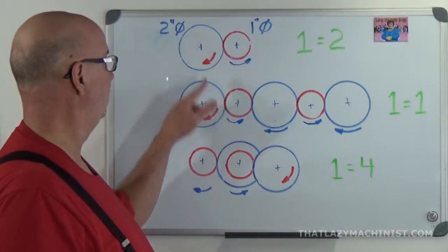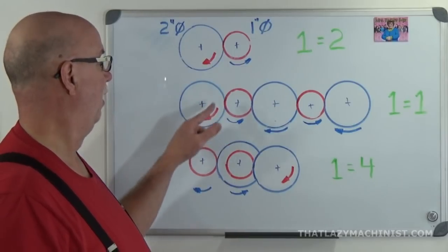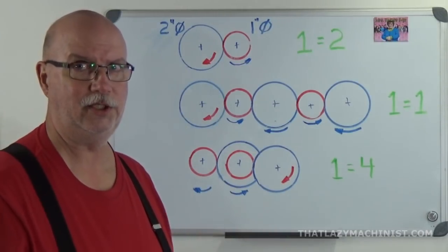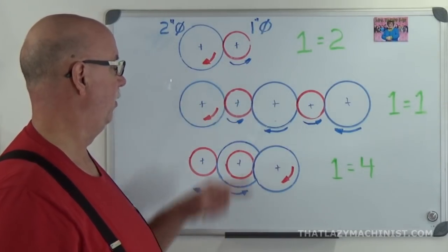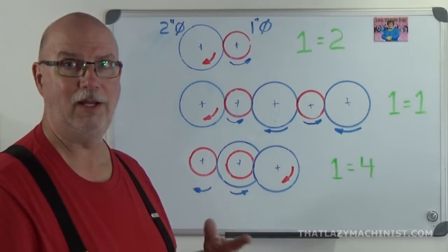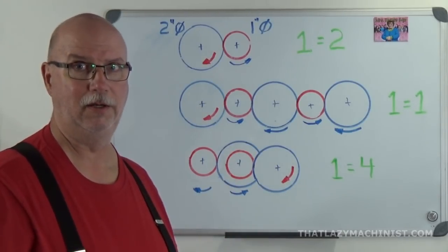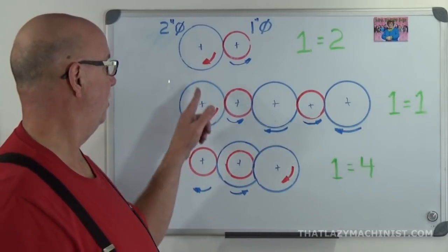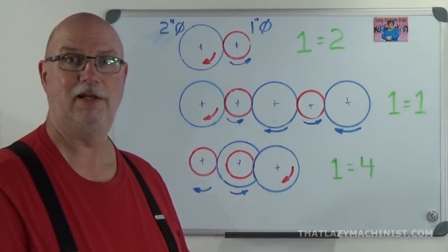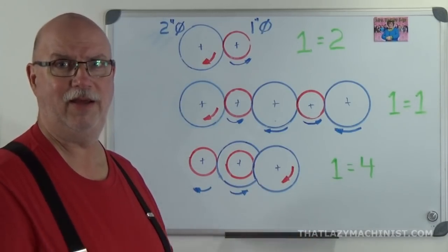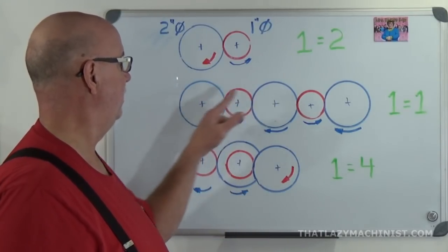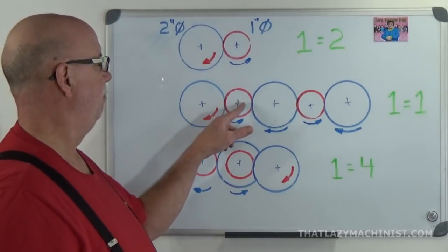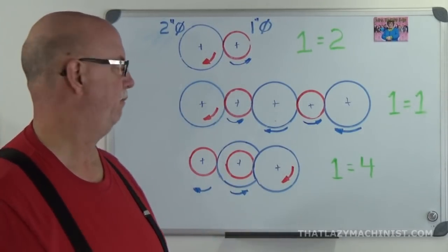And look, I have the same gear, and it's the driven gear, and it's driving the same gear. So I know that relation, and I know that this smaller gear is going to be turning twice as fast as the larger gear. Okay, it's connected to a large gear, the same size as the first. What's that going to do? It's going to annul any advantage that I had here. This gear and this gear are going to be turning at the same speed. And this middle gear, well, just becomes an idler.